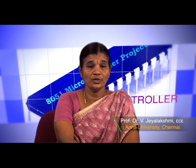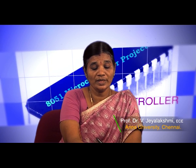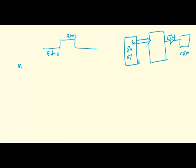So, before starting the program, how we are writing the program means: MOV A, #00H, then move to the particular port, suppose MOV P1, A. After that call delay for the off period, right.